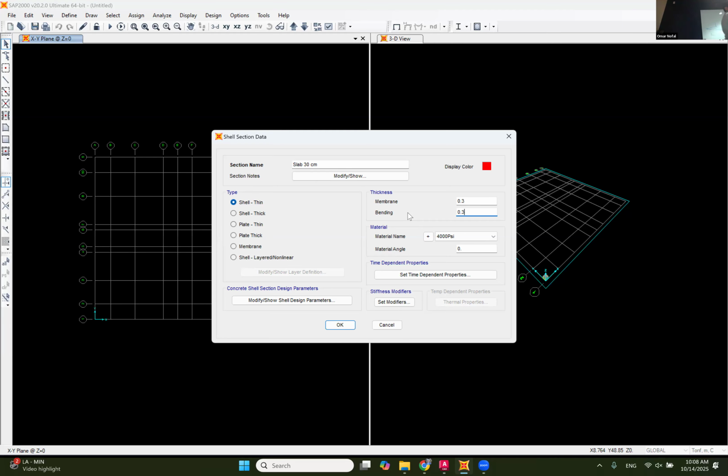So usually this software deals with these things as a matrix. Do you guys remember the degrees of freedom? The degrees of freedom for the plate and membrane were 12, but for the shell were 24. So basically, when you put the load on the plate, the loads are going to move the 12 degrees of freedom, but there's nothing coming that triggers the other 12.